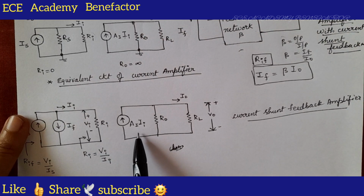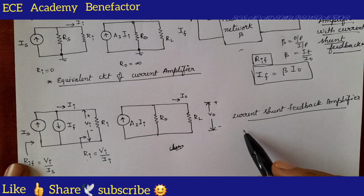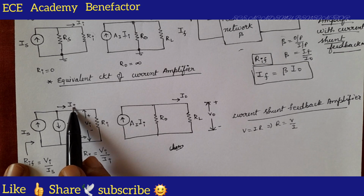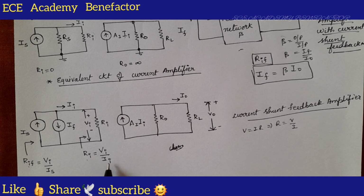Resistor Ri at the output side, AI II, R0, RL. So we have two definitions here. One is Ri, the input resistance without feedback. Ohm's law, V is equal to IR, so R is equal to V by I. So what is Ri? Vi by II. And RIF is the input resistance with feedback, so it will be Vi by IS, the total source current we need to take. The difference is here II, and this is IS.